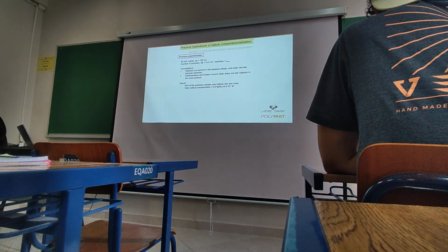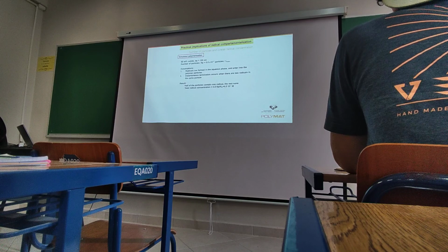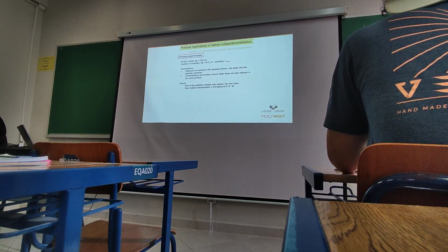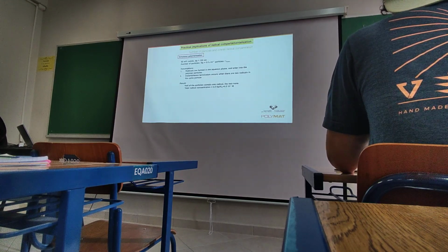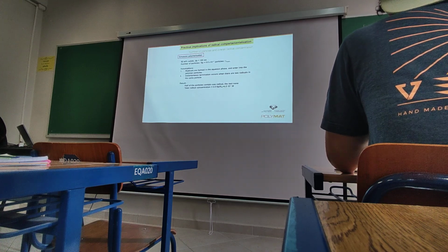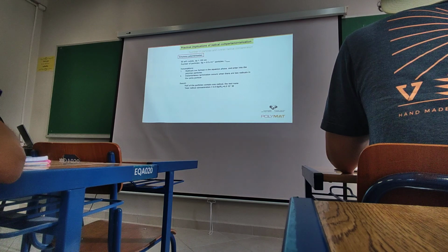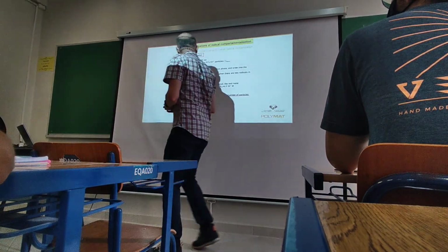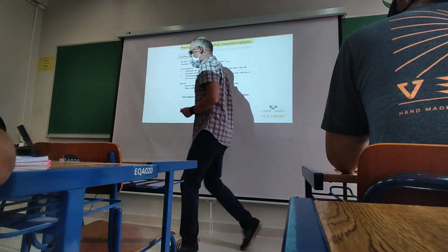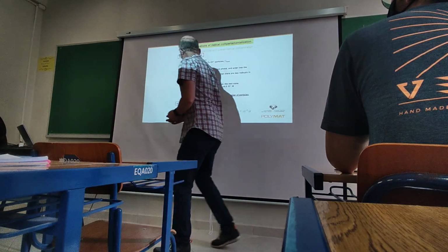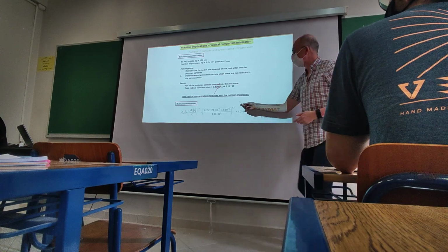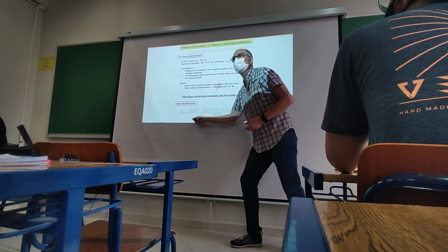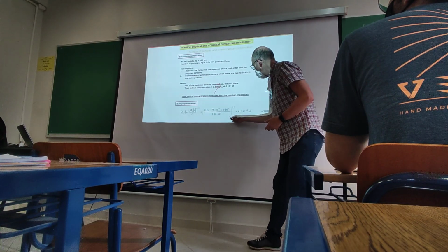So if I increase the number of particles, I can increase the total concentration of radicals. And as I showed just in the previous slide, I can also increase the molar masses. So I can increase the overall radical concentration, I can go faster in the polymerization, and I can increase the molar masses. Okay? The two facts. If you compare this with a homogeneous system, the radical concentration is given by the equation I showed you before. So here, this is always constant.